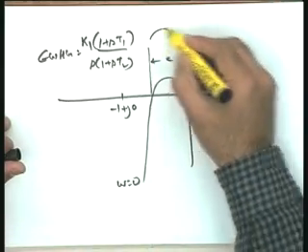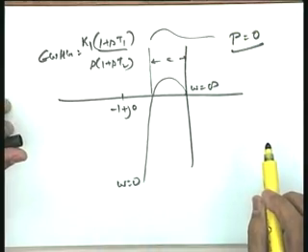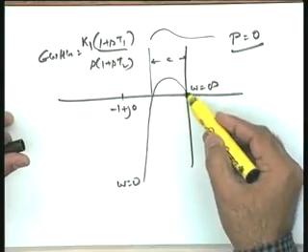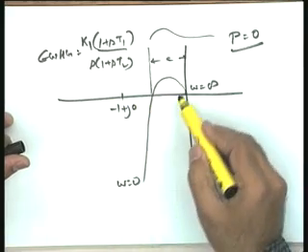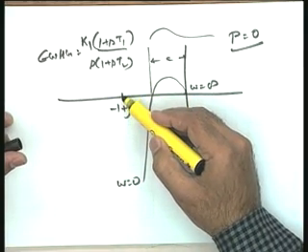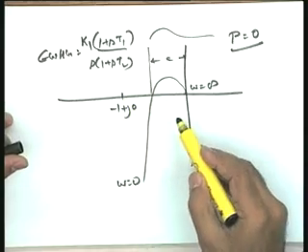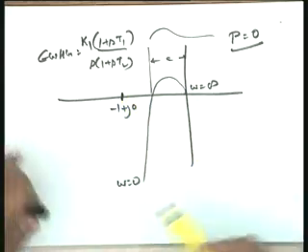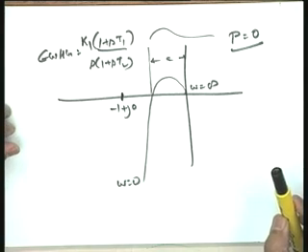You will note that I have taken P equal to 0, that is, the right half plane poles equal to 0. Now, you can see if I increase the gain by a factor of 1 by a, in that particular case the system will pass through minus 1 plus j0 point and hence will become marginally stable, and at most marginally stable. Therefore, corresponding to this particular situation I can say that the gain margin of the system is 1 by a.